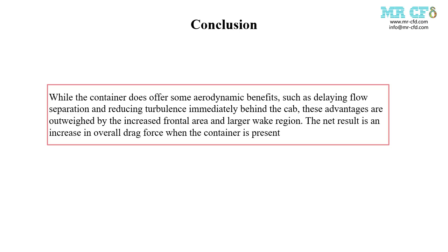In conclusion, while the container does offer some aerodynamic benefits such as delaying flow separation and reducing turbulence immediately behind the cab, these advantages are outweighed by the increased frontal area and larger wake region. The net result is an increase in overall drag force when the container is present.